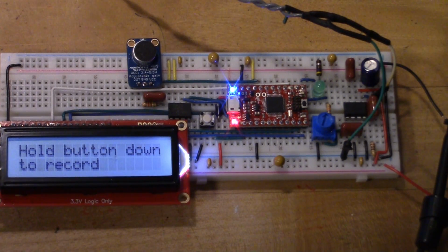We use the SPI RAM in its sequential mode, so in recording, we just send 1 byte to the RAM every time a new byte comes in, and it gets loaded into the next sequential memory address. When we play, similarly, we use sequential mode so that when we read a byte out of the RAM, it goes to the DAC, and the next time we read a byte, it comes from the next sequential address. All we really need to do in the interrupt service routine is keep track of the maximum number of bytes we can write to the RAM and how many we've written so far, to make sure we're not at the end of RAM, and when playing, read until we hit the end of storage.